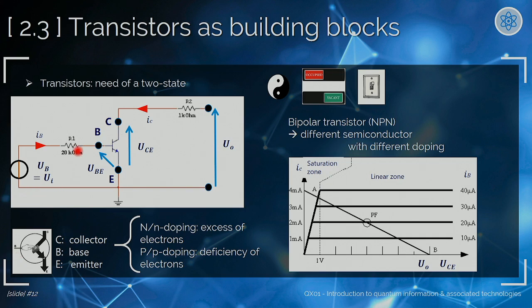This button is simply a voltage across the base and the emitter, where you can change the state of the transistor, deciding to have a transistor that lets a current through or not, and basically have your two states of 1 and 0. You can see here the typical curve, switching on the transistor and then having the linear zone working of the transistor.